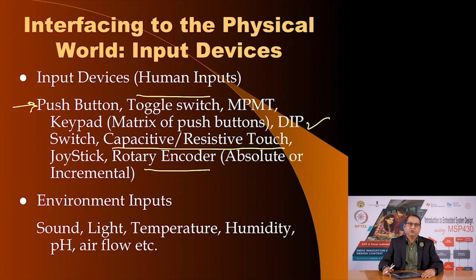Similarly, in audio systems, there is a dial for changing the volume or selecting a song. They do not seem to have any start or end. These are examples of rotary encoders, and usually the cheaper ones are what are called incremental rotary encoders, although there is also an absolute variety of rotary encoders and they are quite expensive.